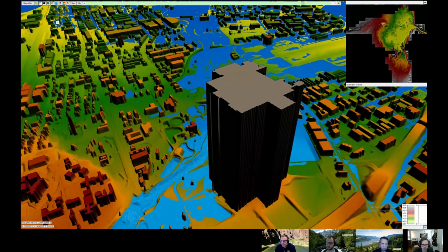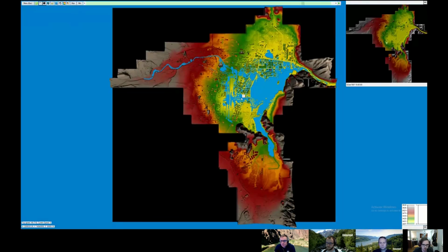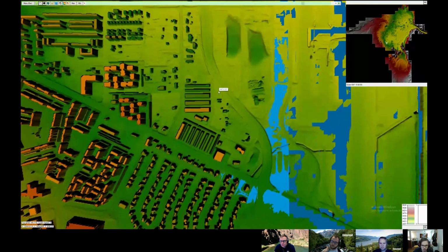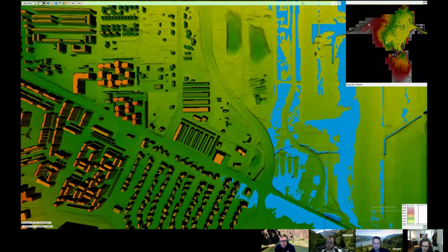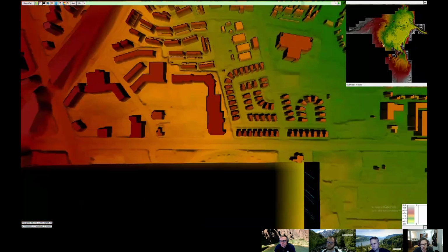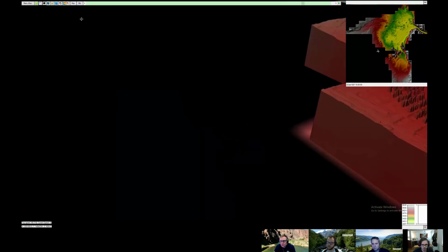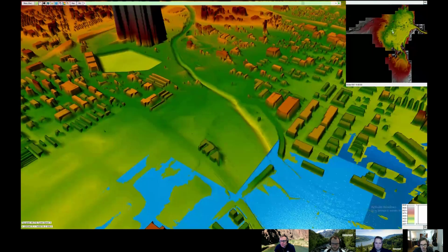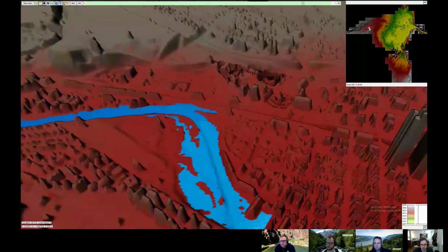If we ever want to go back to the center of the map, like how it would react in RASMapper, you just click this button here. It brings you back to see everything. Another thing, if you get lost, is you have a little mini map here. You can see where you are in relation to the terrain. So if we're off into space and I don't know where I'm at, you can just tell that you're here. If you want to move without dragging or using the keyboard, you can click the mini map and it will just place your camera there. You can actually hold down the mouse and control the viewer that way.